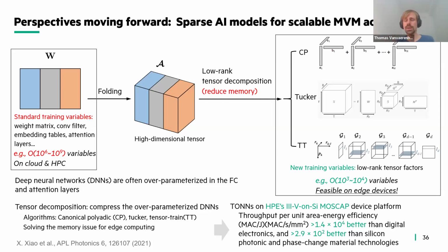So another thing you could do is take the matrix and use some kind of decomposition method. You can approximate this matrix and reduce the elements that you need to approximately represent the information that you needed in the first place. If you do that, you might reduce the number of elements you still need in the end, like going from maybe a million to a billion variables down to 1,000 to 10,000 variables. Effectively you reduce the elements that you need to control on a chip, and that makes it again more feasible to represent bigger networks on the same chip surface. So that's a pretty promising approach.